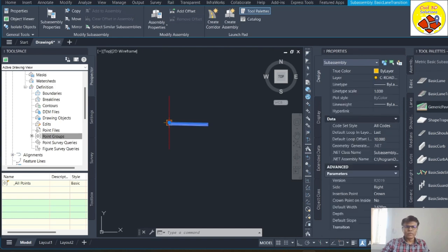So the only thing I'm going to change here is change offset, because for this transition I have to use change offset and elevation, so that it will be good for me to target the offsets and elevations when I work on elevation. So I don't want to hold the offset and change elevation, neither do I want to hold anything. So I just want to change offset and elevation. That's the only change I have made here.